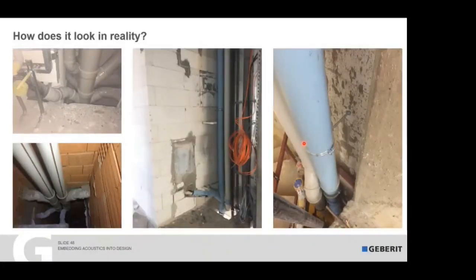And if one pipe is quieter than the other, even when the difference is 3 decibels or less, we cannot even hear it with the human ear. That's why you see that the classification is mostly in 5 dBA steps. If it's just 1, 2 or 3 dBA, we cannot even hear the difference. So that's why it's important to have this differentiation.